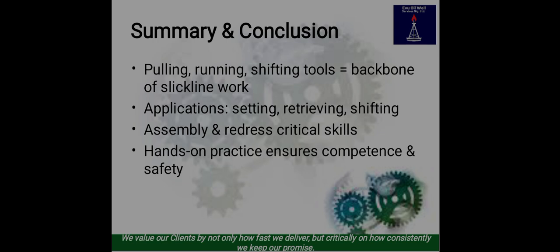The lessons learned here, therefore, are this. Always verify sleeve profiles, redress and function test tools before deployment. Avoid excessive jarring without confirmed engagement. Keep accurate maintenance and tool usage records. Maintain discipline even when under pressure. In my field supervision experience, discipline is what separates a successful operation from a failed one.